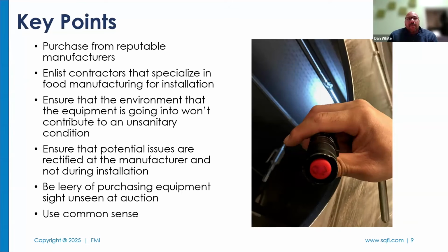Yeah. And just because it's not during the design phase, you can still use your hygienic design checklist on an old piece of equipment. You can still go down through there and say, does it have hollow legs? Does it have bad welds? Does it have threaded fasteners that are visible? So you could certainly